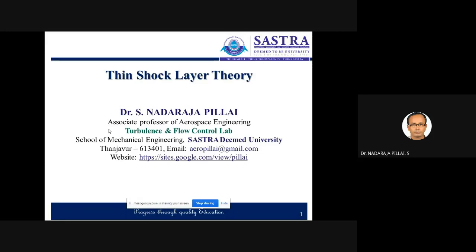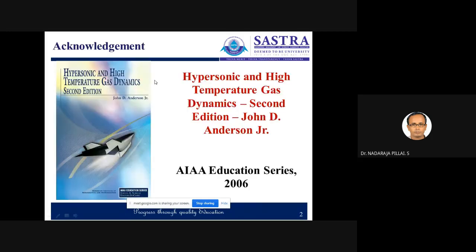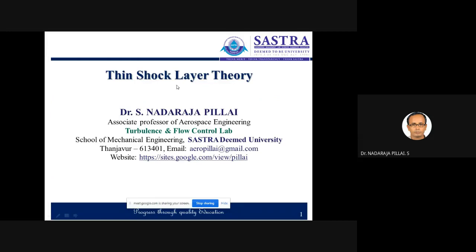Today we will discuss the thin shock layer theory, right? You know very well that, from the basics we have already studied, the thin shock layer is the layer between the shock and the body. In many cases we have studied something called beta minus theta, where beta is the shock angle and theta is the body wedge angle. So let us have a discussion on the thin shock layer theory.